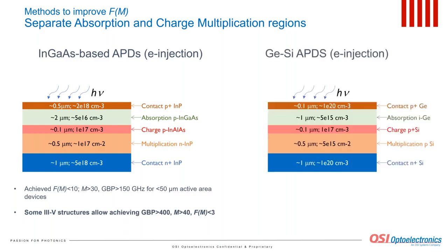The image to the right shows schematically a germanium-silicon APD structure in which the germanium absorption layer is close to the light entry site. Illuminating the structure with infrared light, all light quanta will be absorbed in this germanium absorption layer. Generated non-equilibrium electrons will be swept by the electric field toward the silicon multiplication region at the bottom of the structure, creating the avalanche.